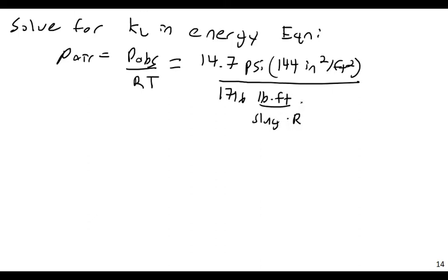If you remember from chemistry class or from other applications of the ideal gas law, you cannot use a scale like Fahrenheit or Celsius. You have to use an absolute scale like Kelvin. Although we're doing English units, I'm going to use Rankine. The Rankine scale is to Fahrenheit like the Kelvin scale is to Celsius. So yes, we're digging out R, which is degrees Rankine.